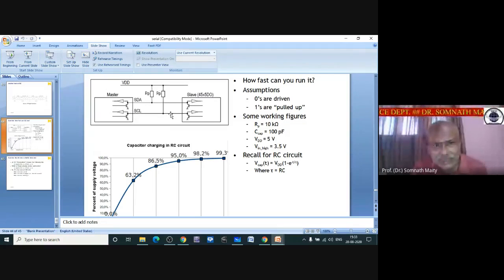The clock line and this port also use open collector type, so that's why a resistance is connected and the supply is connected through the resistance. Here also, that's why two resistances are there. These are required for open collector type ports.